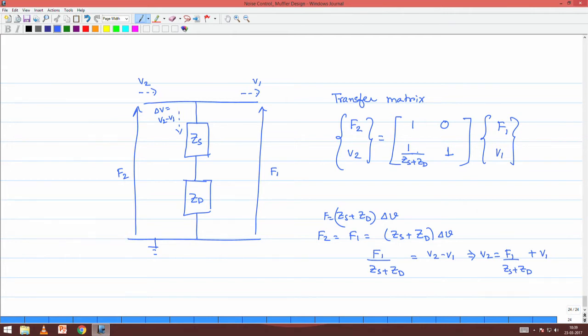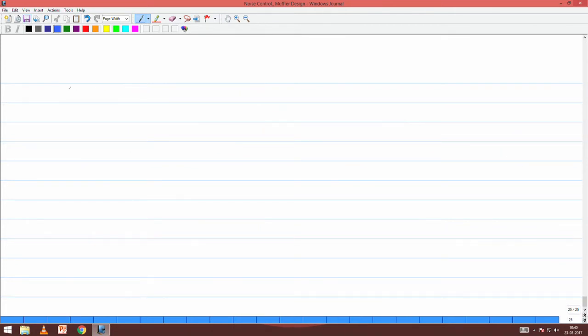So, a spring damper combination element is almost the same as a spring element, except for the fact that the spring element will have an impedance Zs, the spring damper combination will have an impedance of Zs plus Zd, both in the shunt position, right. And now what you will see is that the impedance of, now if you put this together with a mass. So, now let us consider this as example 4.